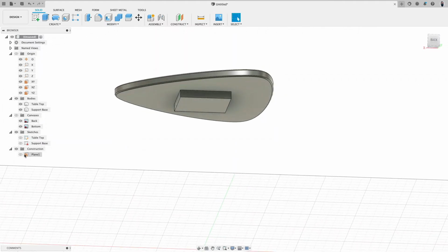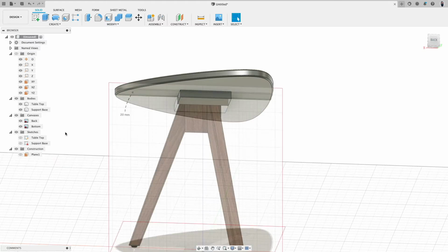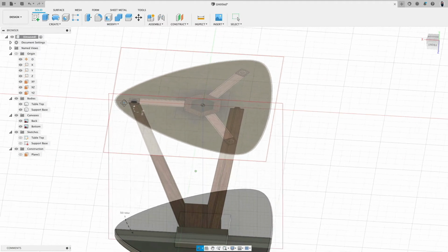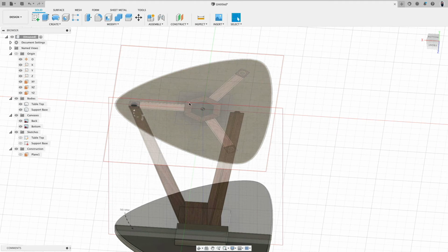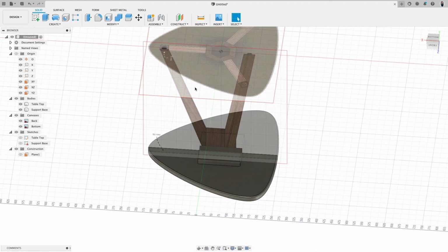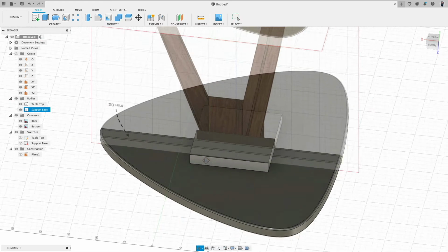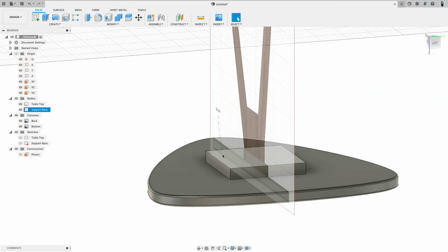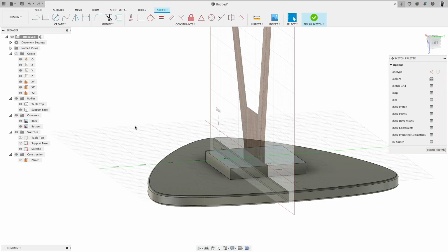Now the next step that's going to be easy to do is, yeah, which one should we do? You see here this 1, 2, 3, 4, 5, 6, so this hexagon. How can we easily model this one? So first we need to put it actually on this plane now. So you see this is actually where the sketch should be on. So new sketch on this face. No, okay, very good.